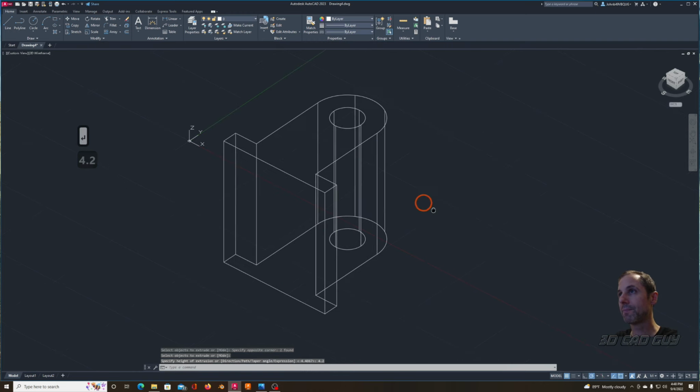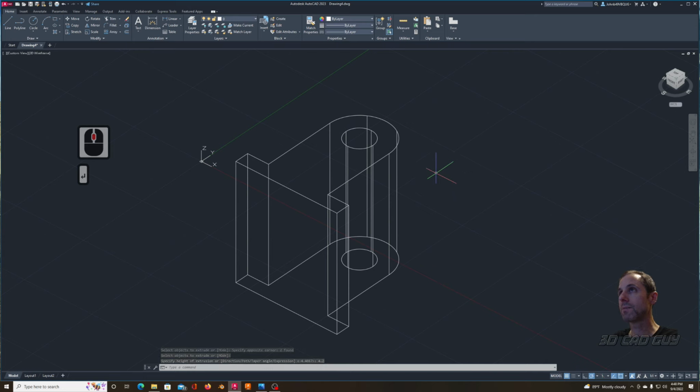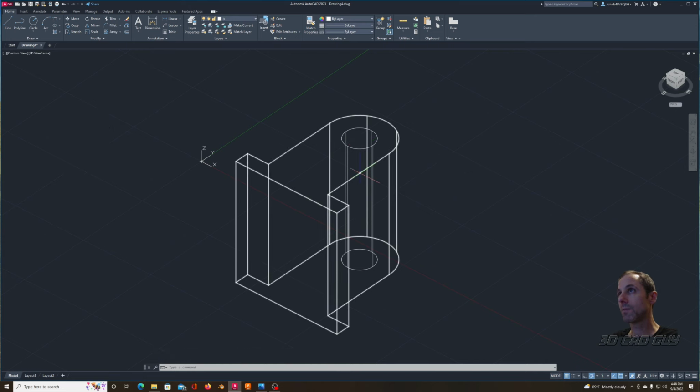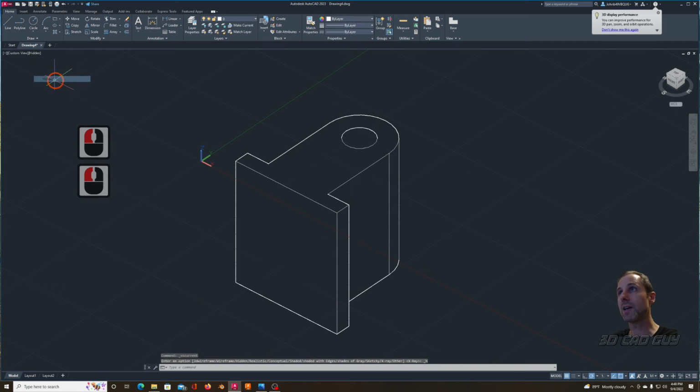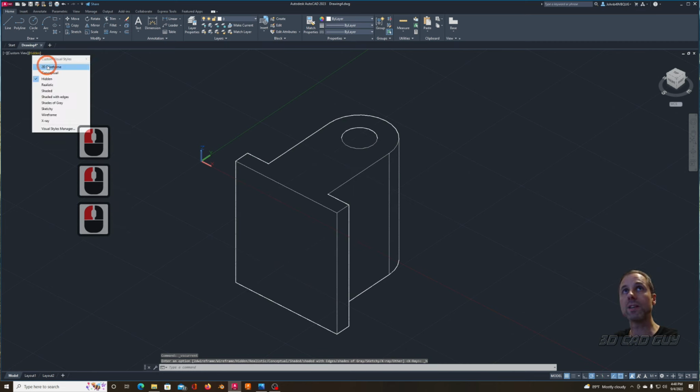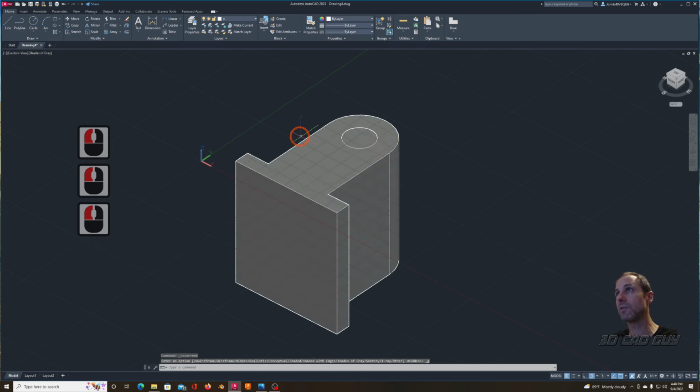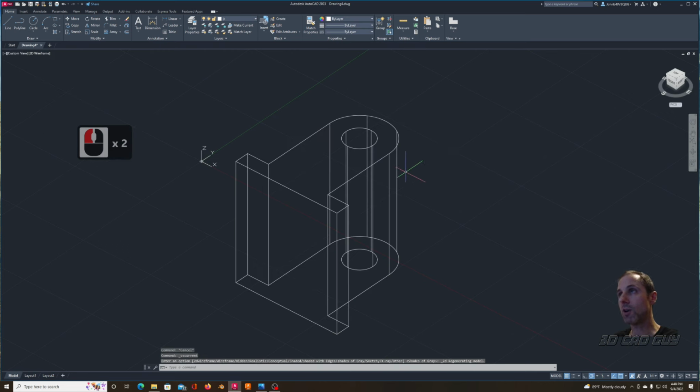That's it. Now in this case, we want to subtract this bore out of this. Otherwise, right now what we have is basically a cylinder inside of this. If you were to say hidden lines, you won't see it. What's better, probably with shades of gray, you'll see it's kind of there, and it's just two pieces. You don't generally want that. Subtract it.